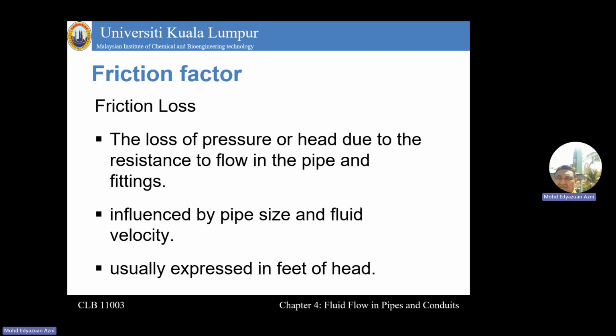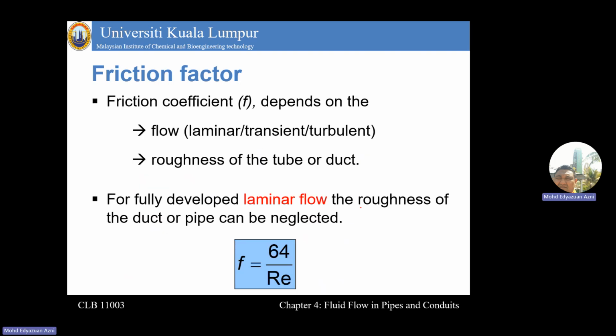So friction factor, or friction loss, is the loss of pressure or head due to the resistance of flow in the pipe and fittings. It is influenced by pipe size and fluid velocity and usually expressed in feet of head. So that is friction factor.